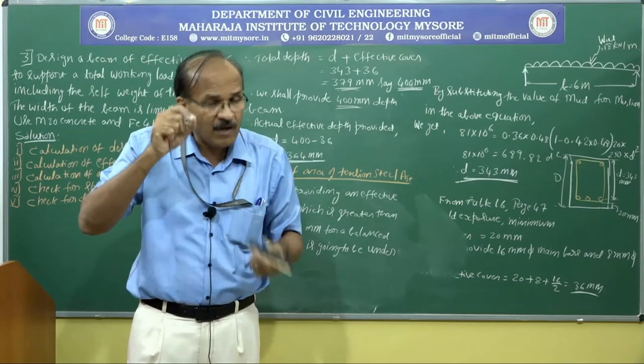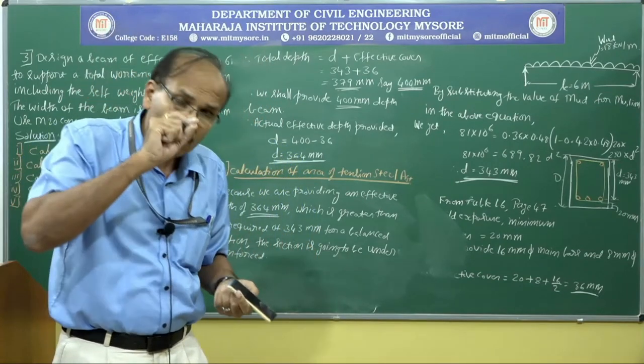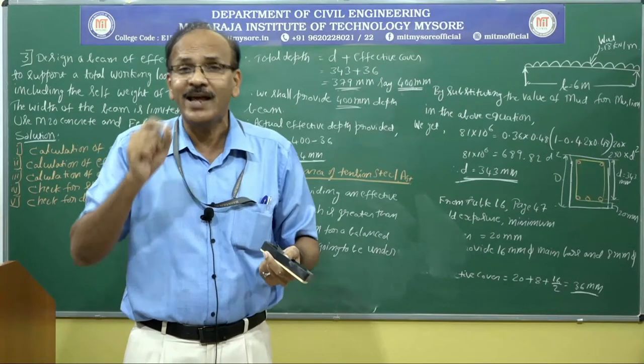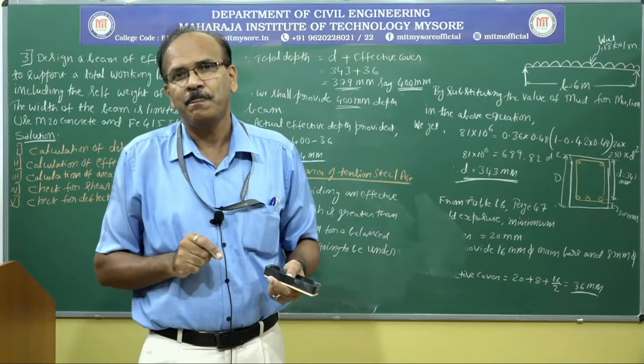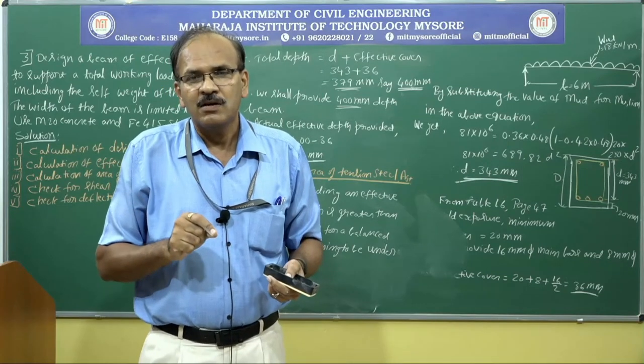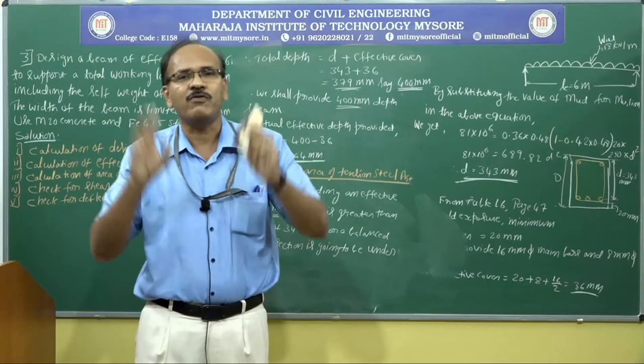So once the area of steel required reduces, it is not going to be a balanced section anymore. Instead, it is going to be an under reinforced section. Okay. So it is not going to be unsafe. It is going to be under reinforced.